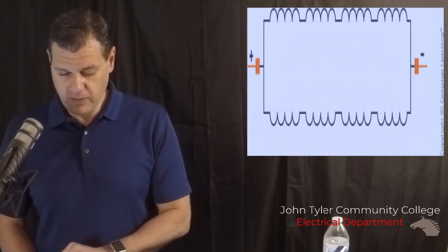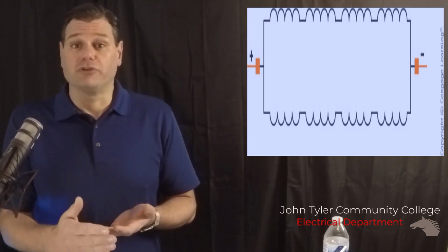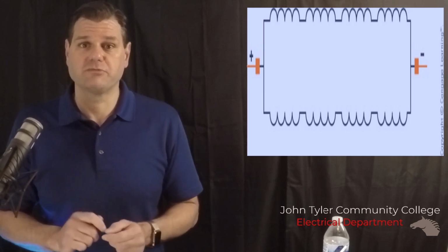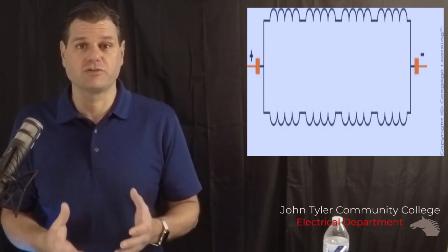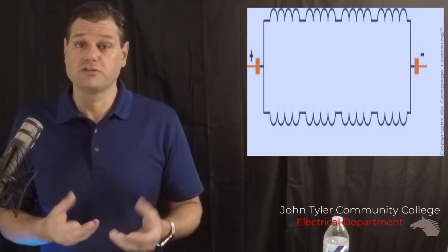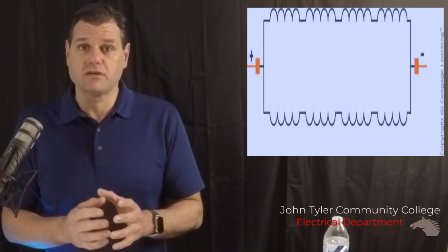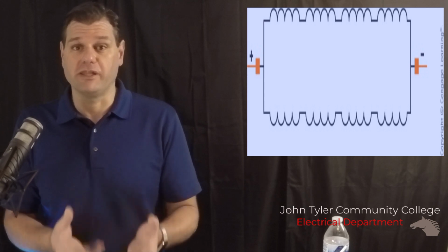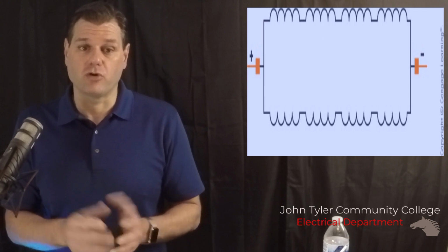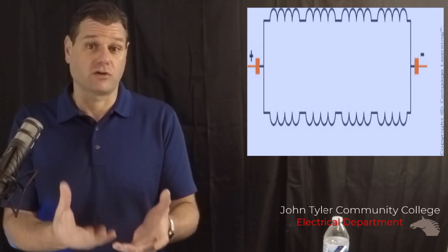The next we're going to talk about is our wave wound. Our wave wound is going to be very high voltage but very little current. In our generator world, this would be like a hand cranked radio or a flashlight or charging a cell phone through a hand crank. That kind of generator can produce a lot of voltage relatively for what it is, producing 5 volts in some cases, and very low current, milliamps. So you're not doing a lot of work, a lot of current flow, but you're overcoming the potential of the battery and allowing it to recharge a battery or charge electronics in a radio.